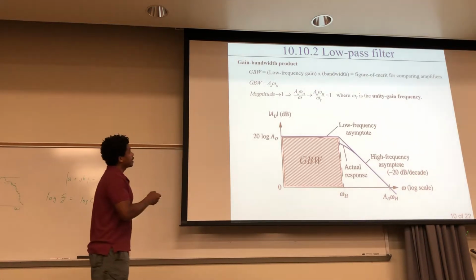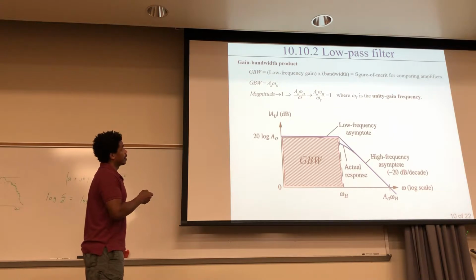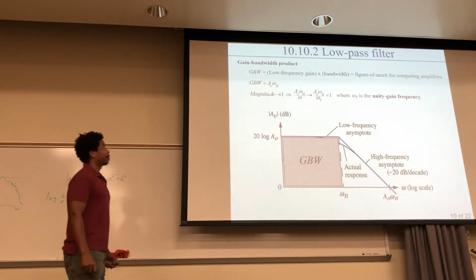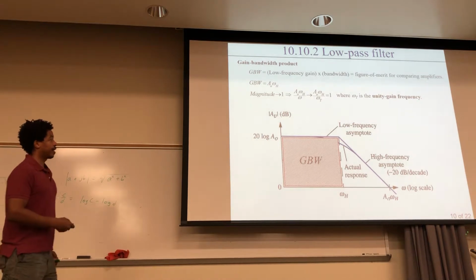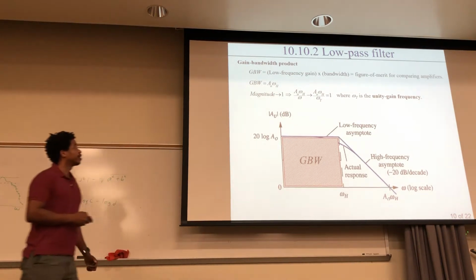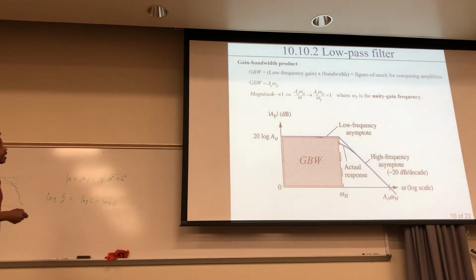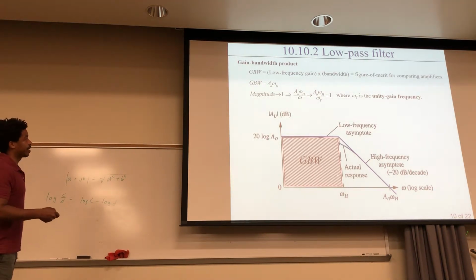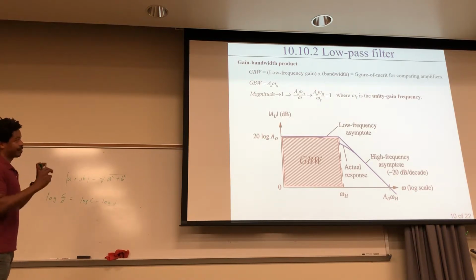And this is the frequency, so remember this came from the magnitude. And the question is what frequency makes your magnitude 1? And that's your unity gain frequency, just for terminology. Now I blocked in what this value is right here, symbolically.